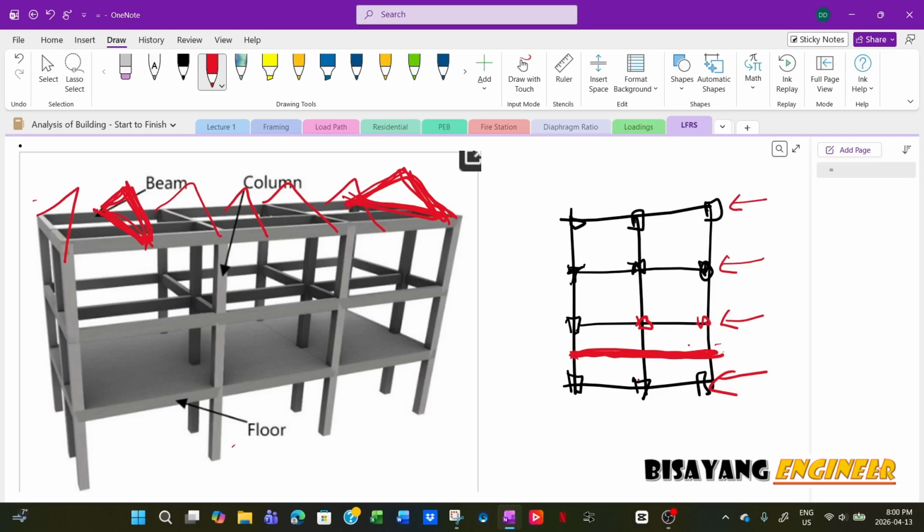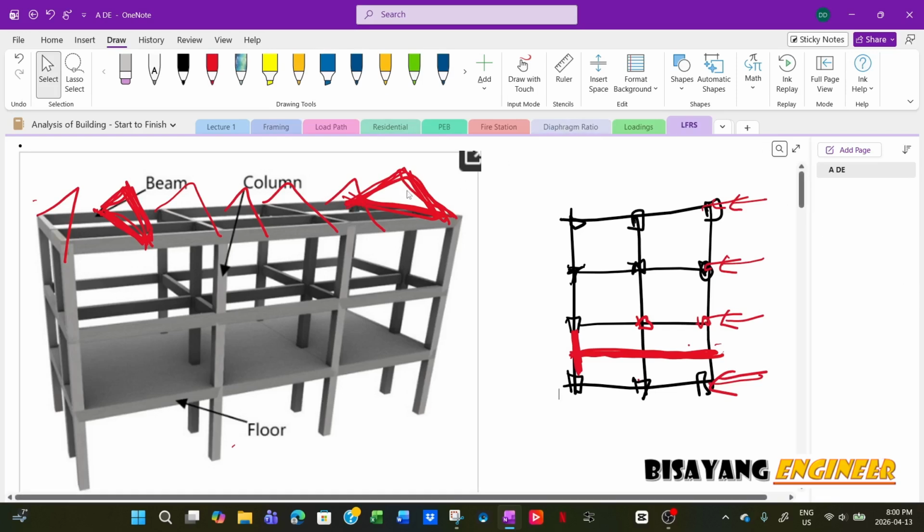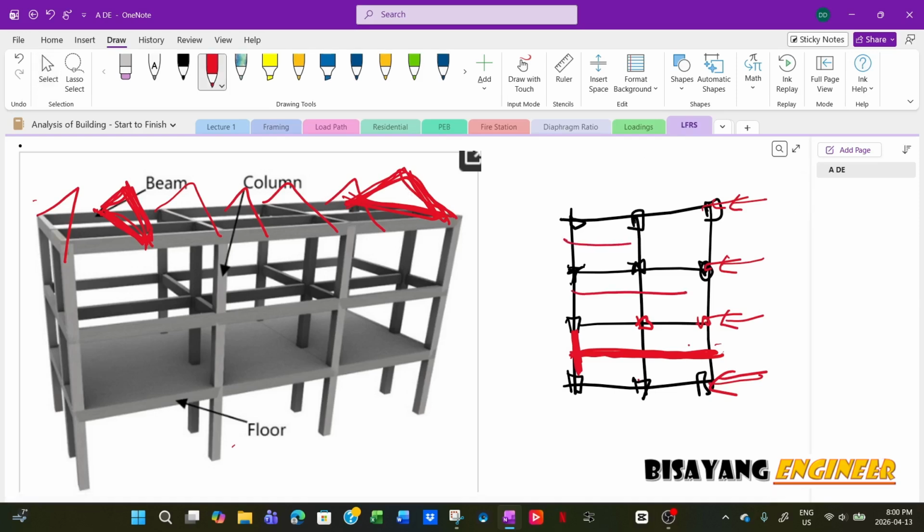So if you apply the load directly at the beam-column joint, then you basically neglect the forces that are being carried by the beam, and that is under design. So you have to apply the load where the load is supposed to be. If you have a truss in between, then you apply the load. Now, if this is also supported right here laterally, then you have to apply that one also.